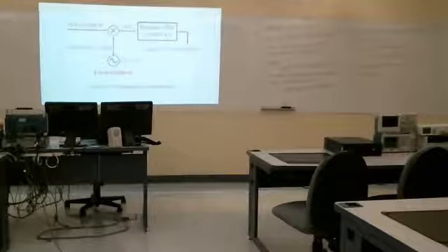If I want to listen to a different radio station, turn our tuning knob, which changes the center frequency of our bandpass filter, and pick up a different station. Early receivers used a tunable bandpass filter to select a station.